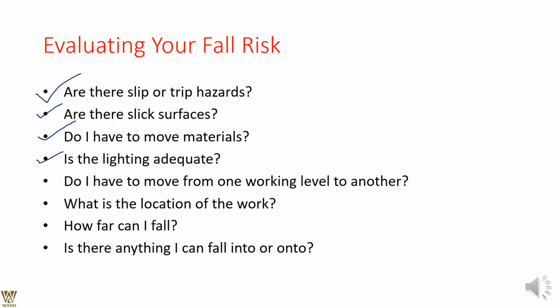Do you have to move from one working level to another? We are talking about level 1, level 2, level 3, and so on. What is the location of the work? Definitely, and always look into the consequences. How deep can you fall? Is it 4 feet? Is it 15 feet? Is it 30 feet? What is the effect? Is there anything that you fall onto, and what are you falling onto? If you're falling onto a chemical, catastrophic outcomes will follow. So please avoid such things.